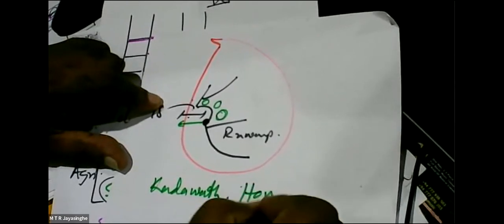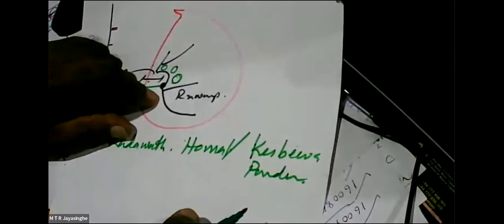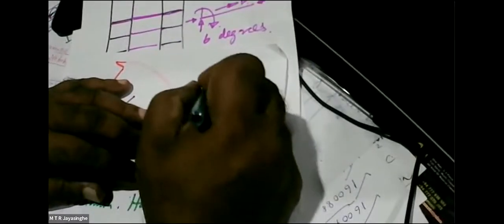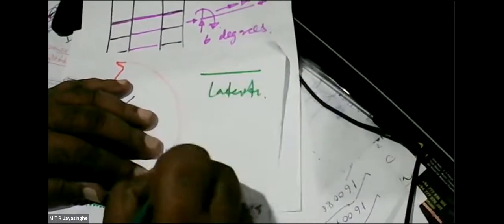So with all these things, now the situation is changing very fast, and where you will find most of the future tall buildings will come is at Kadawatha, Omagama, then Kasbeva, and all these areas like Kahatuduwa, and then Panadura. That is again, at the Galnigama interchange, because Galnigama is again high ground. So these are the main places where we can expect many tall buildings, many medium-rise buildings. And in all these places, we have high ground, laterite soil, and very low water table.